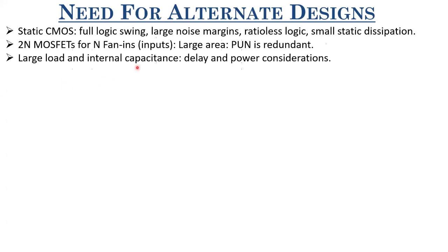And the contribution is large. Also, the internal capacitance would be large, I mean, the capacitance at the internal nodes. If these two are large, then definitely delay will increase, and also dynamic power dissipation will increase, because when calculating dynamic power dissipation, you have to look at the power dissipation by internal loads as well, right? So input capacitance is also 2N times Cg.